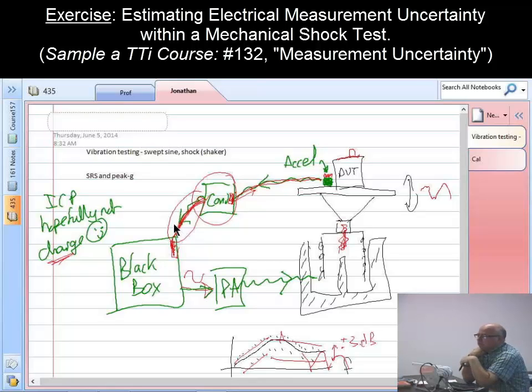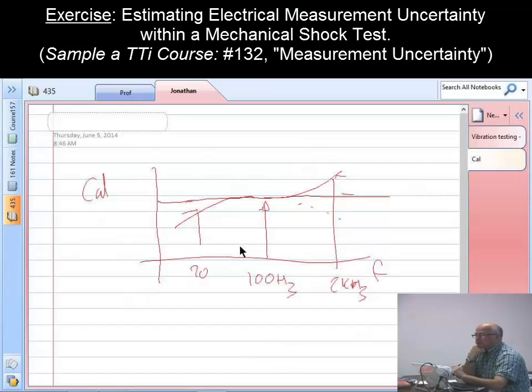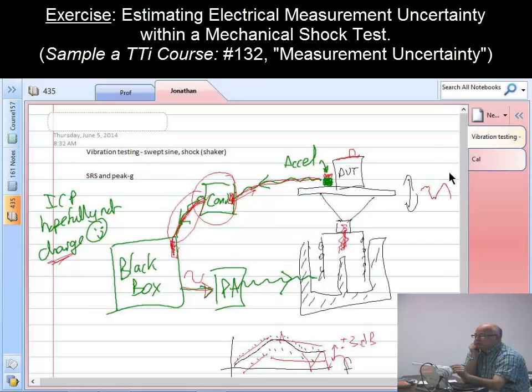So to frame the question, if I'm trying to find the measurement uncertainty for this system, would I be most concerned with the one accelerometer that's going to be providing the data? That's going to be the main source because of the calibration curve. Yes, okay. And I have never yet seen a system that actually has multi-point calibration going into it. It just has a single value: the sensitivity, 91.6 millivolts per G. Done. There's no reason why they couldn't, but nobody does, or I haven't come across it, and I doubt that your system does. So that will be the main source of uncertainty right there.